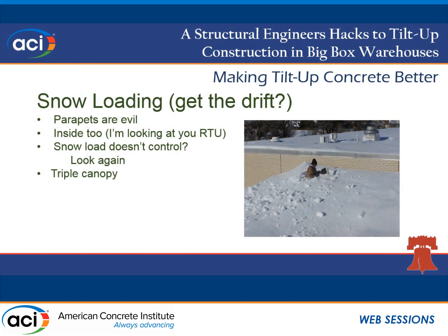Another thing to cover real quick on snow, and I ran into this on a couple of projects. Keep an eye out for RTUs. There's a limit in ASCE 7 that says anything less than 15 feet doesn't need to be designed for snowdrifts, which means if you have an RTU that's 15 feet long or a screen around an RTU that's 15 feet long, guess what you got? You got snowdrifts.